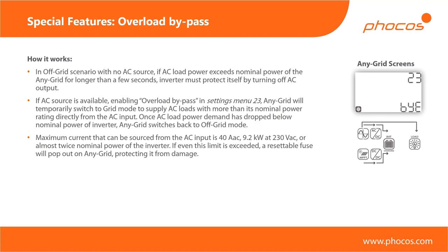So you will want to provide that 2 kilowatts out of your battery if the sun isn't shining, for example, at night. And what will happen is it'll take a certain amount of time for a grid-connected inverter to realize that it needs to power this 2 kilowatt load, not from the grid, but instead from the battery. It needs to basically power up the whole conversion from your DC battery to the AC, etc. And this might seem strange to you, but this will take anywhere from half a second to a second up to 1.5 minutes, which is, of course, insanely long.